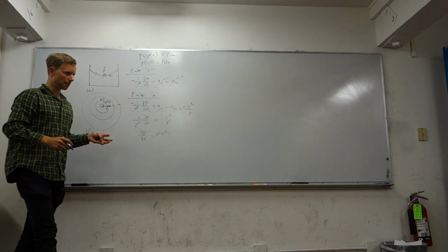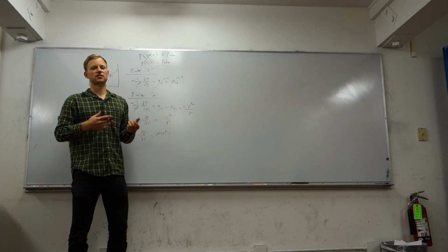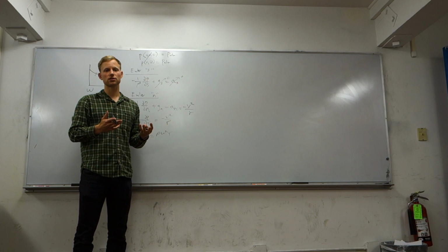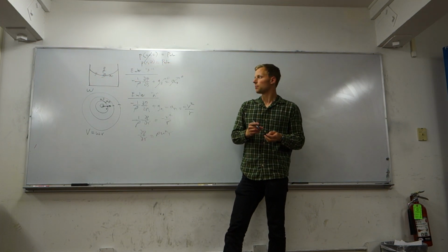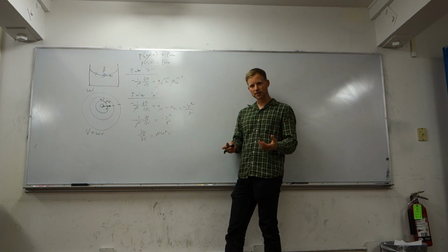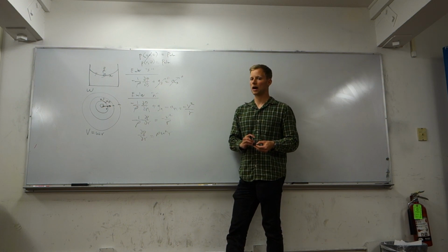And then just remember here that the Euler equations, to put them into perspective, are nothing more than a simplification of the Navier-Stokes equations. The Navier-Stokes equations, we don't go through them in depth in ME70, we introduce them, but those are the most general equations of fluid mechanics, and coming out of ME70 it's important to realize what they are and to be able to understand how we get them.